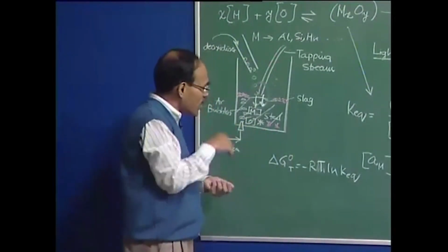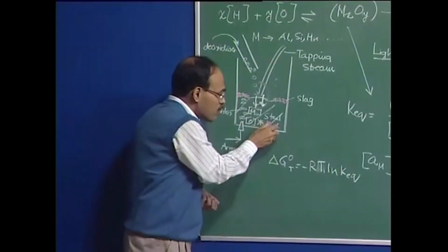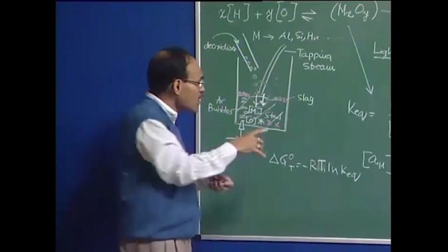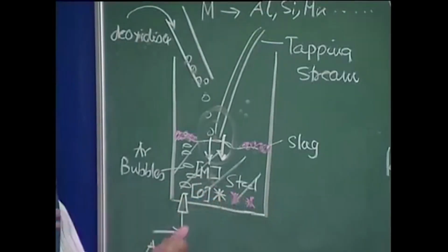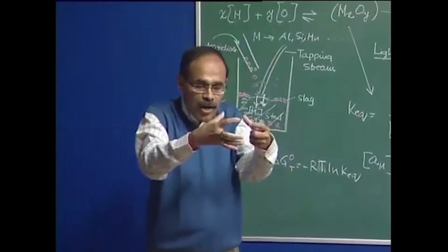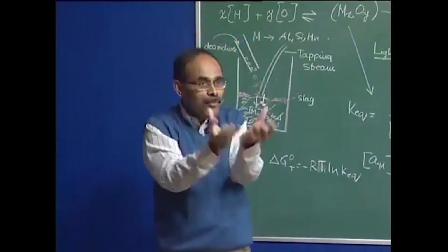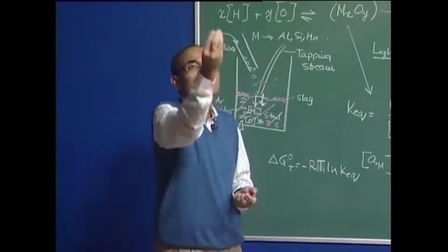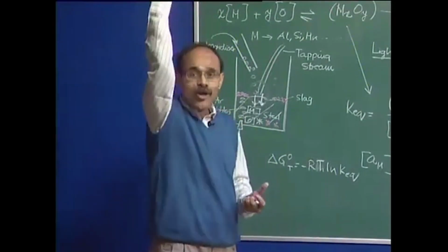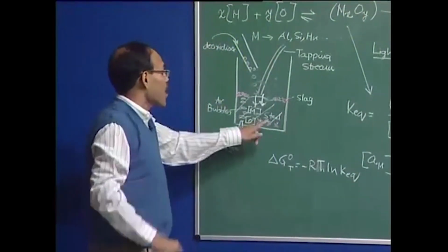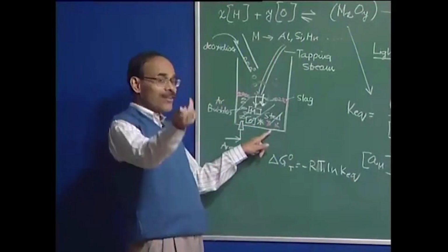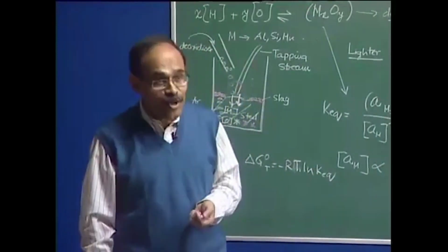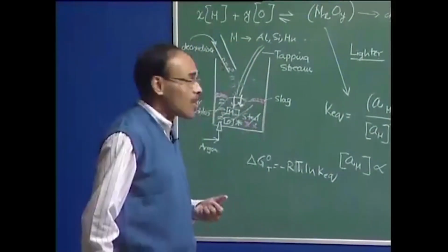But one important thing is that solid deoxidation products do not tend to form bigger masses. On the other hand, if we have liquid deoxidation products and they come together, they immediately form a bigger particle. As you all know, a smaller particle will have a smaller rise velocity, and a bigger particle will have a much larger rise velocity. So we would like to have bigger particles, and therefore a liquid deoxidation product is perhaps more desirable to us than a solid deoxidation product.